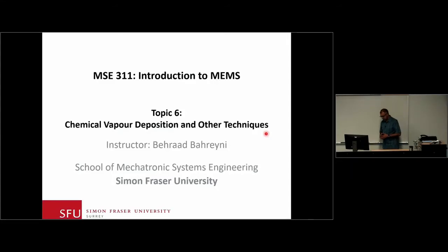All right, so the remaining deposition techniques that we're going to talk about have a little bit of a chemical flavor to them. We talk about bonding at the end of this lecture, but we discussed thermal oxidation as, let's say, the most basic film growth mechanism that we know. Talked about physical vapor deposition, and now we want to make things a little bit more complex and actually take advantage of the chemistry in addition to the physics.